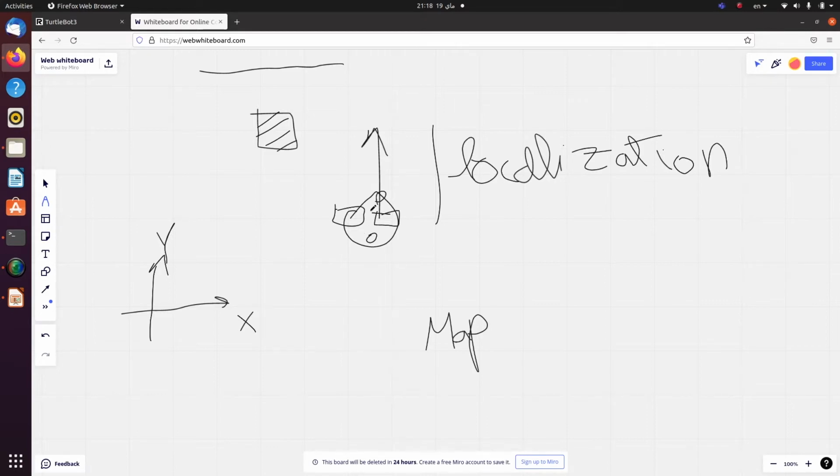How? The robot has a sensor here called a LIDAR. What a LIDAR does is that it produces laser beams, all right? And once these laser beams hit some object, the laser beam reflects and gets back to the LIDAR, and the LIDAR computes the distance to that object through the computation of the time of flight. It's basically like sonar. And the LIDAR is rotating, so we've got a family of LIDARs called 360 LIDARs, which produce several beams in all directions, in all the 360 degrees.